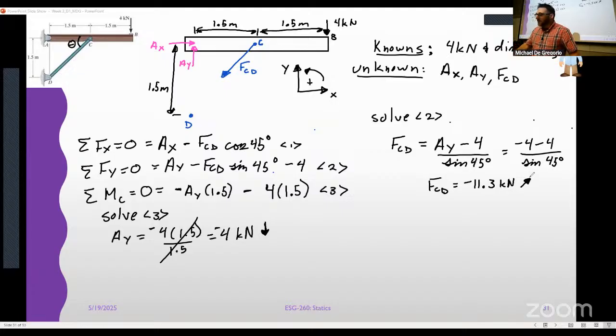When we start talking about trusses, it's going to be really important whether we're in tension or compression. But for this in particular, right now, not. But it's interesting, right? Because we've got these forces pointing down, that means that in order to counterbalance my reaction and my applied force, this needs to react going this way. If I'm pushing down on the end, I should be compressing that, right? Doesn't that make sense? That this should be under compression and not in tension.